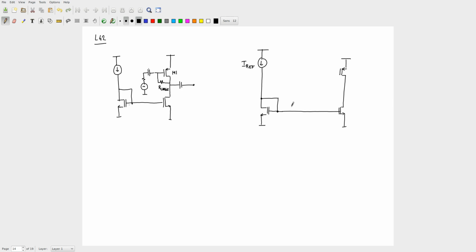Okay. And then I want to use a current source to bias this transistor also. So, what can I do? We have done some things like this earlier. I can put another transistor here, right, and connect its gate to this line, and then go upward and connect a PMOS transistor this way here, correct?